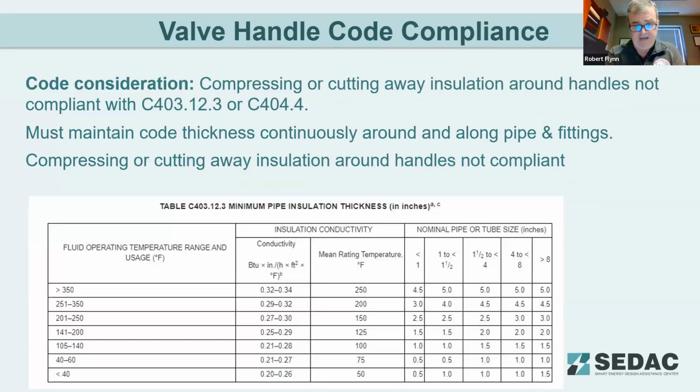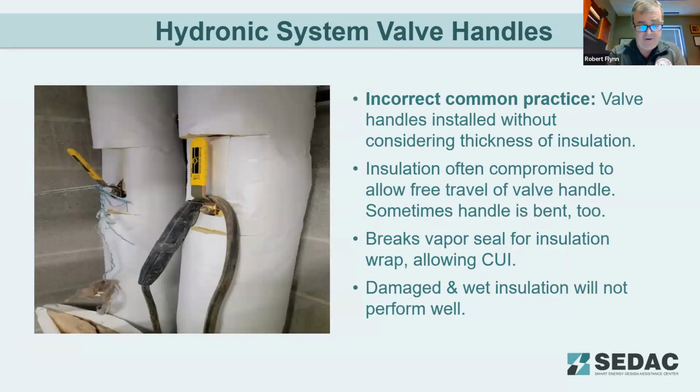And if he or she was going to do it correctly, they should have put some kind of sealer, even if they were going to walk away with that project being done. Not saying that it's a correct way to do it, but if they really wanted to do a professional job, they would probably want to put some kind of sealer to cover that little yellow insulation exposure that you see. Otherwise, it's not really serving its purpose as a weather barrier to the inside of the pipe.